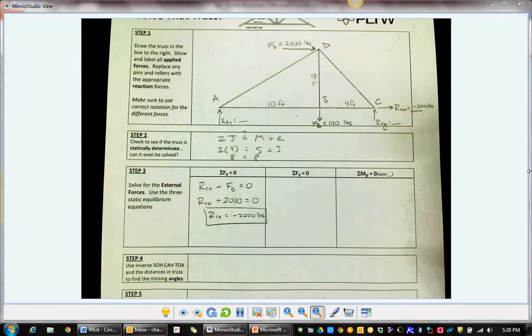If there's 2,000 to the right on the truss, there's only one other X force. You might have known that was 2,000 that direction. But again, I'm trying to teach my students to not make sign errors, and the conventions I teach about always moving in the positive direction seem to clear that up. But it does seem to match with what I would expect. 2,000 that way if it's going to have to be 2,000 that way. I'm not going to change that mid-problem. I will take care of that when I redraw my truss down here in a second. I'll flip the arrow around.